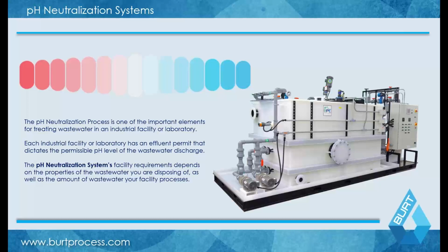A pH neutralization system is an important element of treating water in industrial and laboratory facilities. Essentially, if you have a building, whether it's a lab space, semiconductor fab, pharmaceutical, general industry, even aerospace, really anything where you're handling some kind of chemical-based waste, you're probably going to need to treat it prior to discharge to allow for in-compliance discharge to your local municipality. And at the end of that system you have a pH neutralization system, which is designed to treat the aqueous waste that comes in from the various applications.